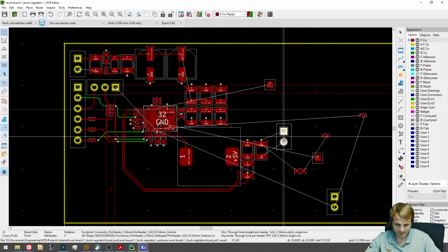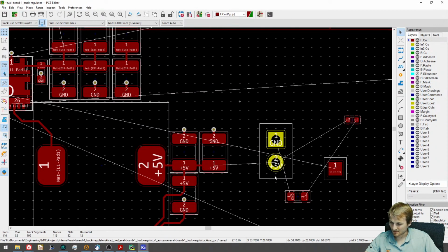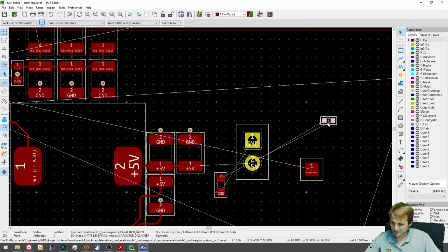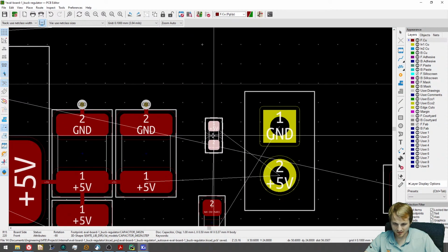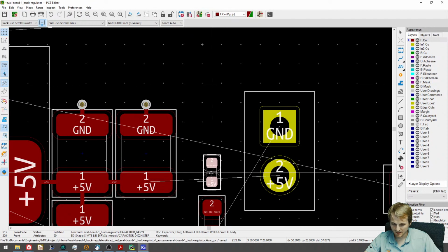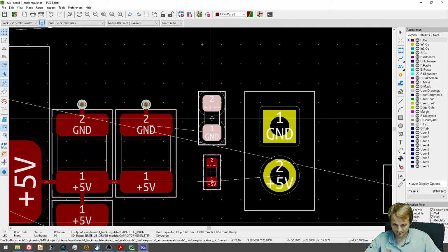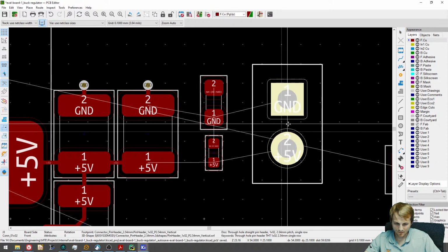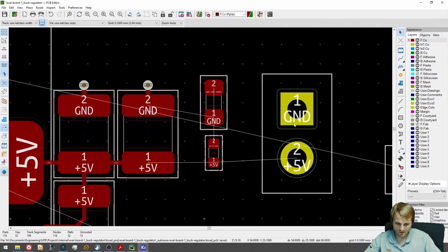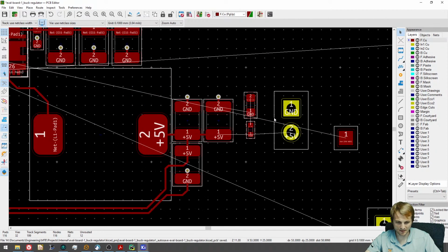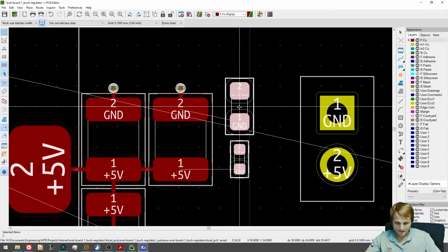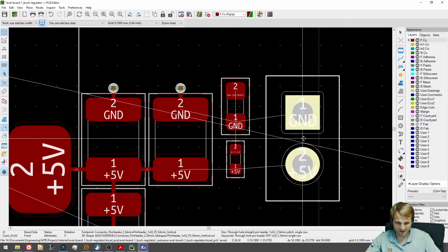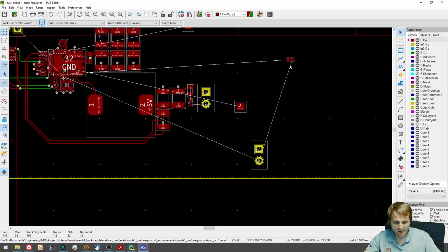Okay, so 2.5 volt output. Now we have our resistor and LED. And then obviously we'll be changing our output connector, because obviously a 2.54 millimeter pin header will not source 15 amps. It could try.